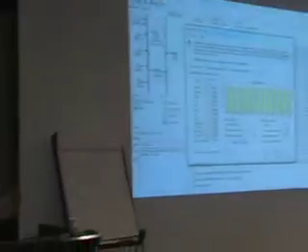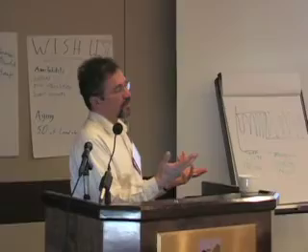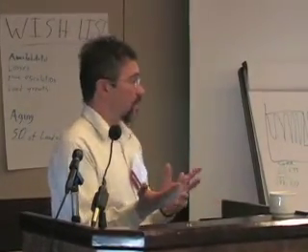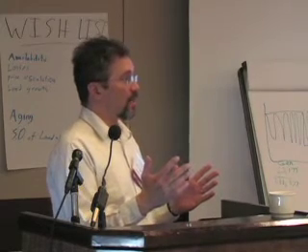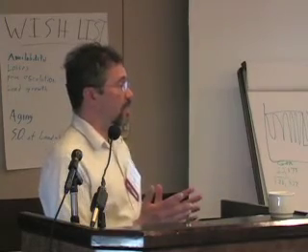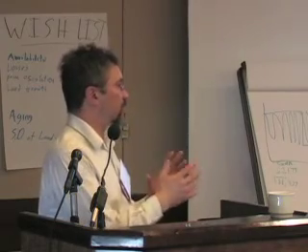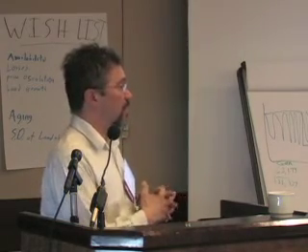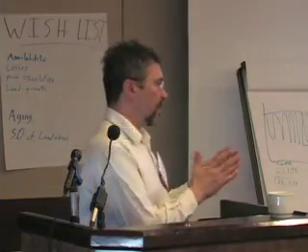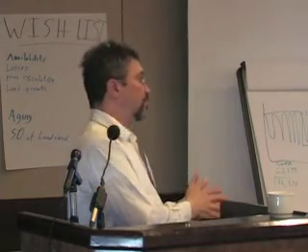If you're modeling with simulation time steps of 60 minutes, but you have 10-minute data, it averages the 10-minute data over the 60-minute period. So that's kind of a waste, but it can do it. If you have 10-minute wind data and 15-minute load data, and you want to do a 10-minute load step, it chops and averages the data correctly for you. It depends what you're trying to do, whether you want to use the shorter time steps. It takes longer to run, but it's probably more accurate.